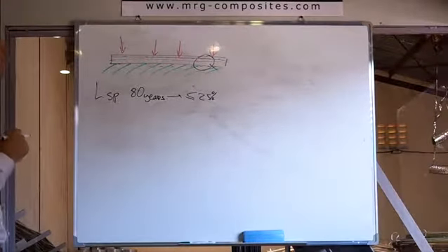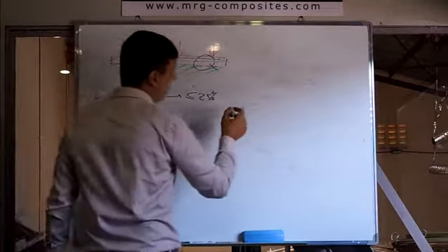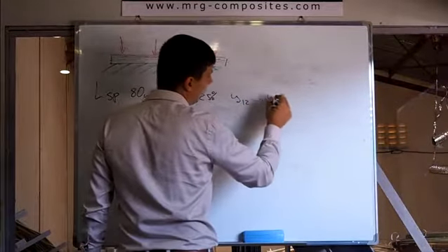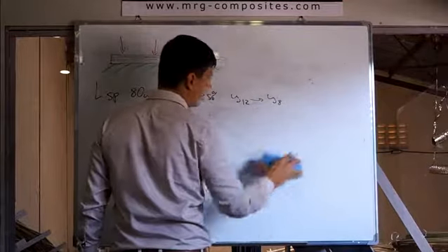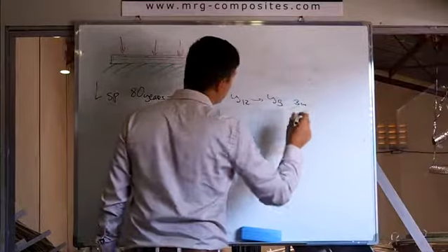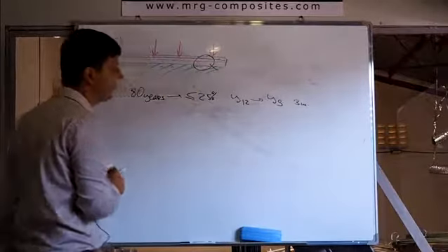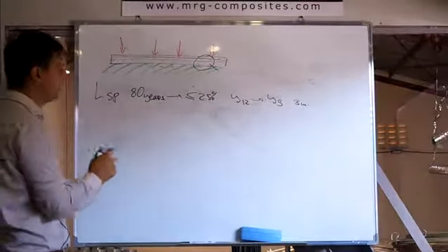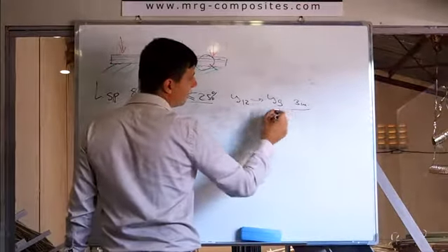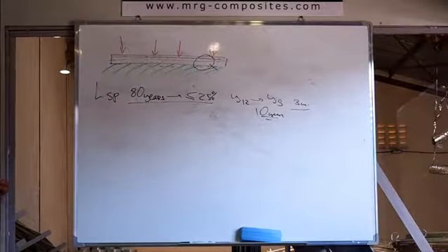This is the maximum. Okay, let's compare with steel. We had Y12. In 10 years, it becomes Y9. So it's 3 millimeters, which is, guys, more than 20%, 25% for 10 years. So for FRP, degradation is 25% for 80 years. Here, degradation is 25% for 10 years. This is durability. That's the difference.